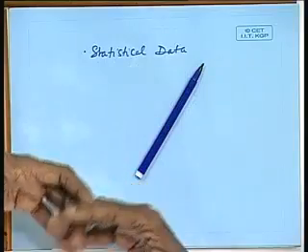So, the best way to do is to find out what statistics says. If you have got a large number of ship data, then can we make a statistical analysis and say, since a large number of ships of all types fall in a particular pattern, the resistance falls in a particular pattern, maybe my ship will fall in that. So, I can estimate my ship resistance and say it will be within plus minus 5% of the actual resistance.